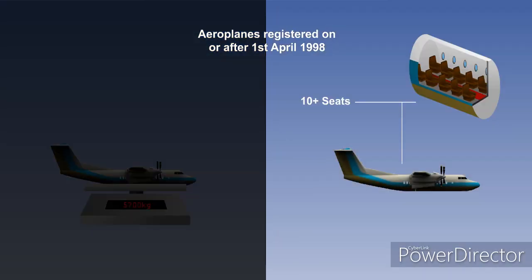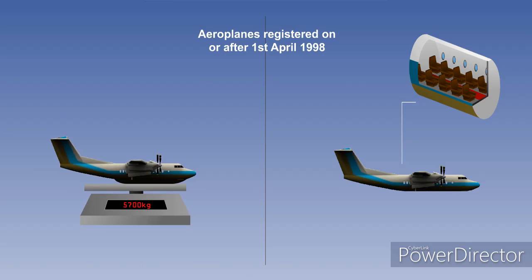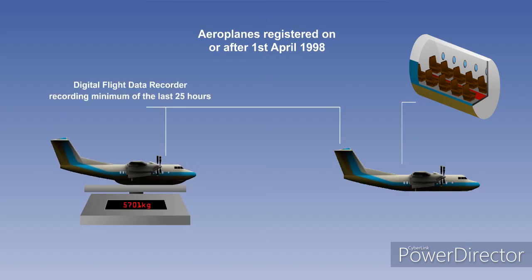Aeroplanes with more than 9 seats that are multi-engine turbine powered, or aeroplanes weighing more than 5,700 kilograms, require a digital flight data recorder capable of recording a minimum of the last 25 hours of its operation.